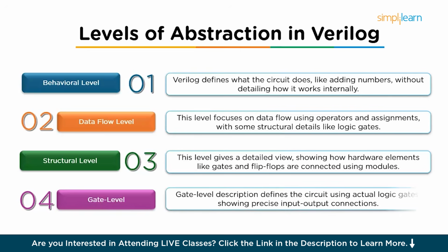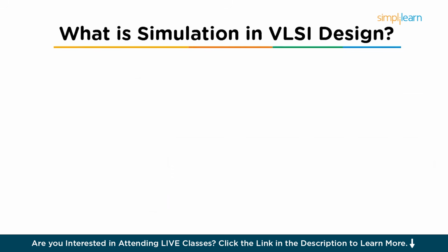Then comes the gate level, the last level. Gate level description focuses on the actual gates used in the circuit and how inputs and outputs are connected. Verilog can be used to define a circuit entirely in terms of logic gates, creating an accurate low-level representation of the design.